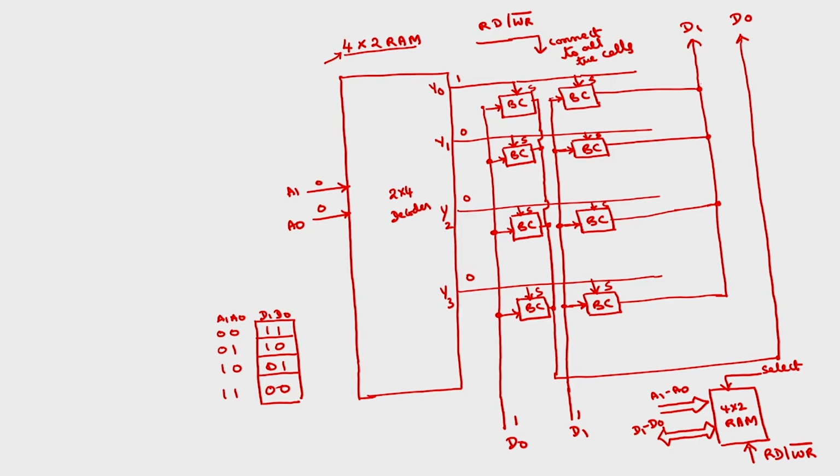So, with this we will go for the expansion of the memories. We have discussed the basic structures of random access memory and read only memory. Now, we will see, regardless of whether it is read only memory or random access memory, how to extend the size. Because if I take 8086, 1 megabyte of memory can be connected to the 8086, that is the maximum memory capacity.